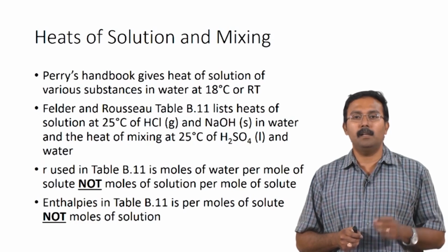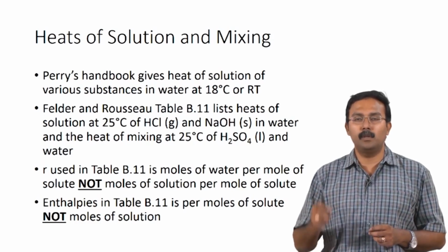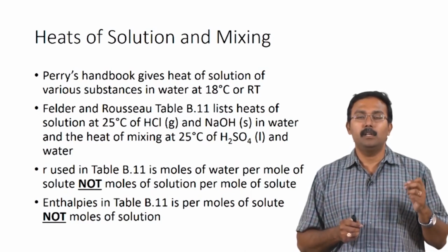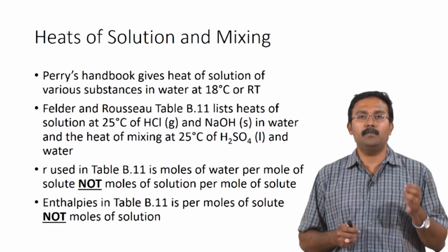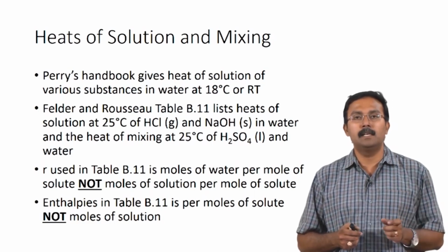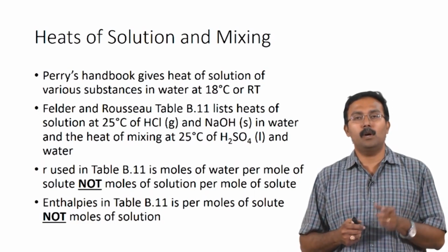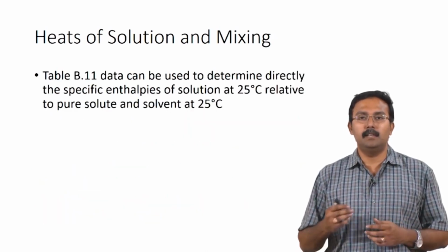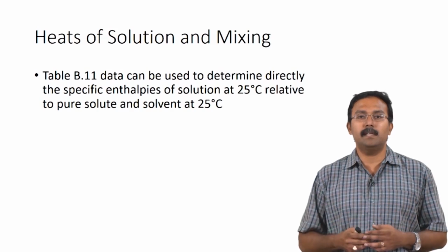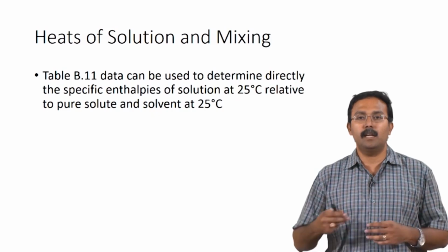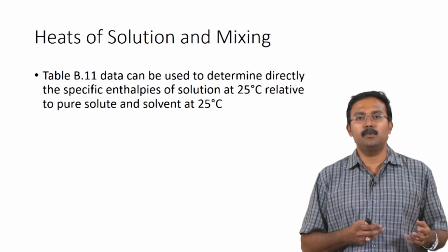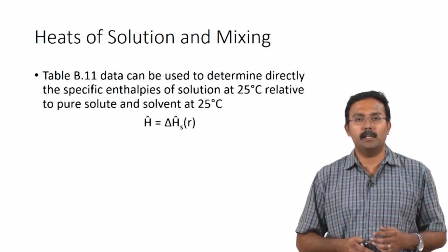Enthalpies in the table are also given as moles of solute, not moles of solution. Again, using the same concept, when you prepare the enthalpy table, you would have to use the appropriate moles for the moles in and moles out, or the moles initial and final. Table B11 data can be used to determine directly the specific enthalpies of solution at 25 degrees Celsius relative to pure solute and solvent at 25 degrees Celsius, which indirectly means that the reference state which is used is pure solute and solvent at 25 degrees Celsius.